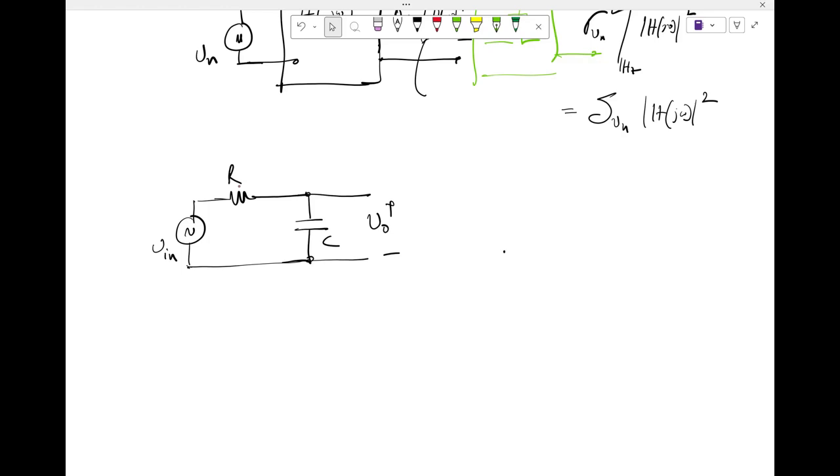But there should be a noise source because I have a resistor, which means even though I have not explicitly mentioned it, it is your job to understand that there is a noise source. If noise analysis is asked for, then you have to replace the R with its noise equivalent model. And what is the noise equivalent model? Noiseless resistor with a voltage source in series. So basically, this is a noiseless resistor with a voltage source in series.